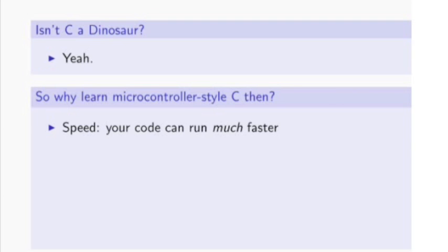If you run it directly, it takes 1, so that's approximately a 40 times speed up if all you're doing is flipping pins back and forth. You'll be doing more stuff like math, and that will make the C comparison not quite as drastic as a 40 times speed up. But your code will run a lot better if you write it yourself and pay attention to it. It's harder to do. There's a trade-off.